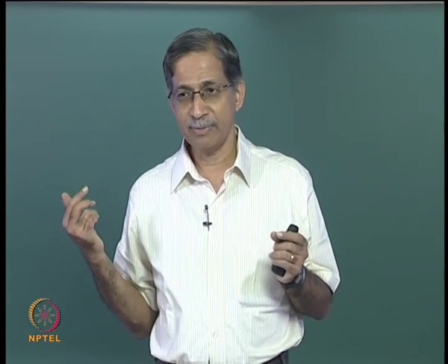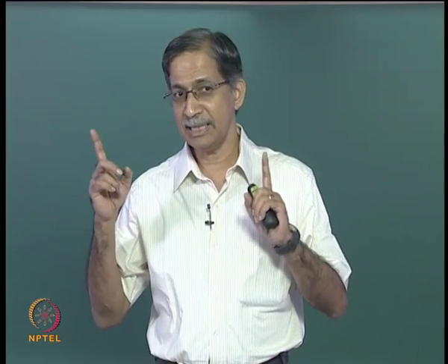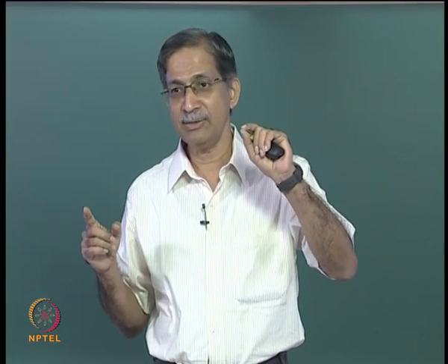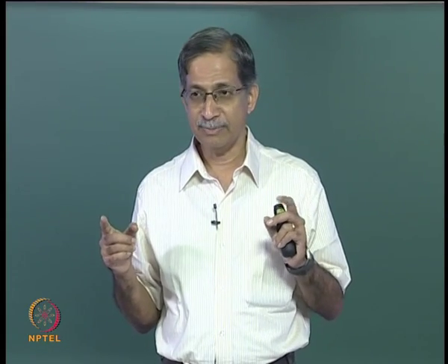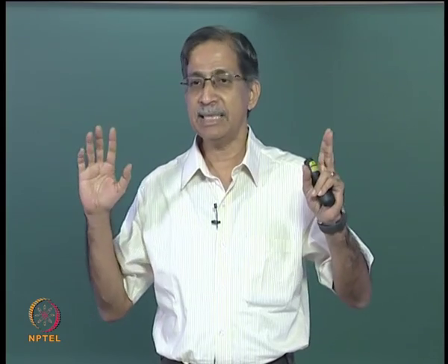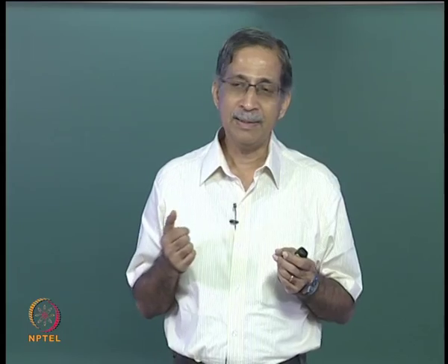What's the size of the matrix? Space truss element, at each end you can have 3 independent degrees of freedom. So it will be 6 by 6, okay.